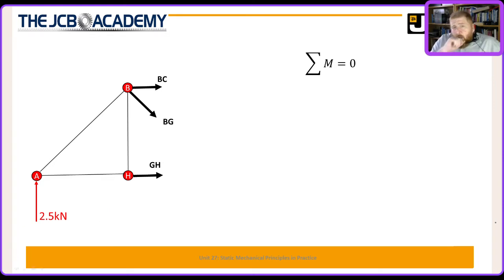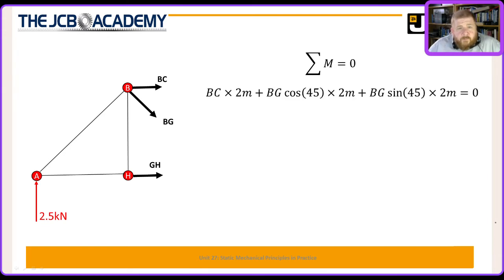However, sorry, I said my convention was typically that anti-clockwise moments are positive and clockwise moments are negative. In this case, I can see from this diagram all my moments are going clockwise. So I have made the decision to modify my standard for this calculation alone and just make everything positive, rather than making everything negative.